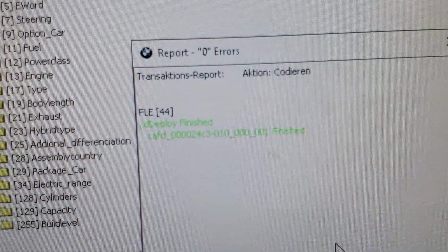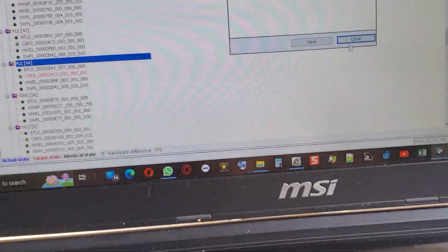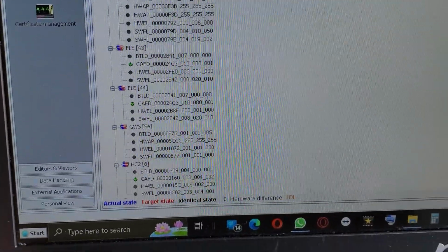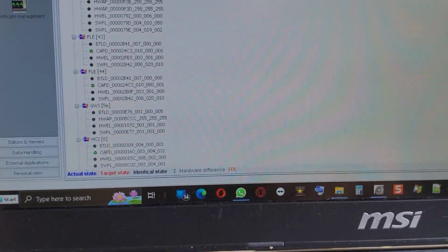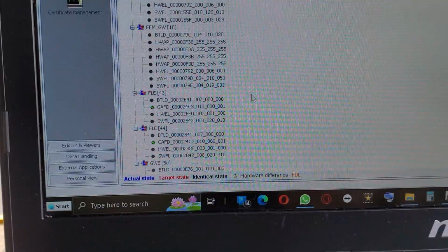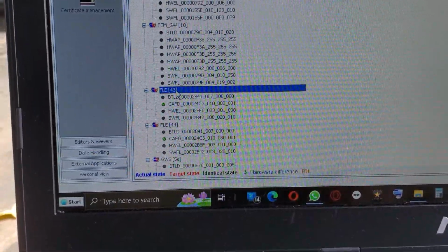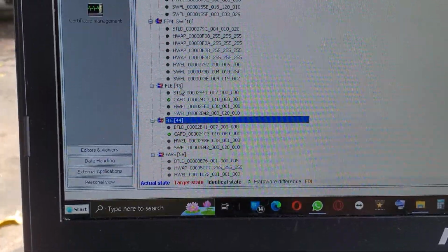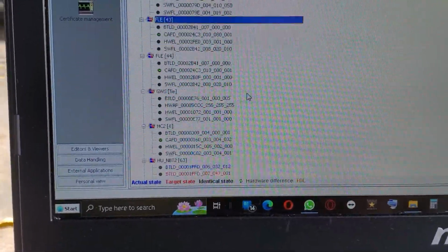There's a file written there. Good. Then we click the read ECU button here. It should be black. There it goes. Alright, we're done with that. And it shows that the other headlight model is also okay. 43 is okay. 44 is okay. So both of them are black. Alright, so far so good, no big deal.